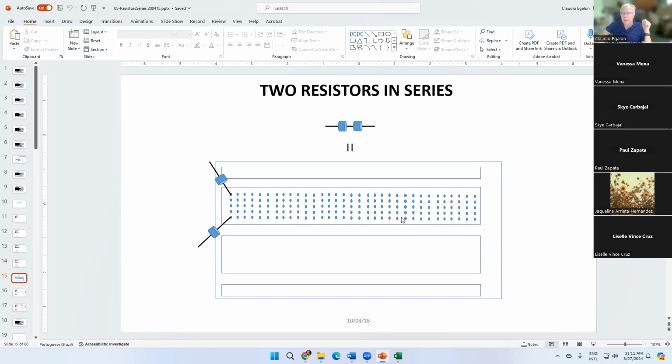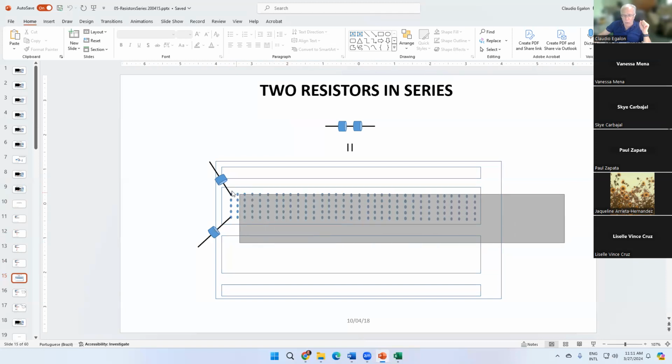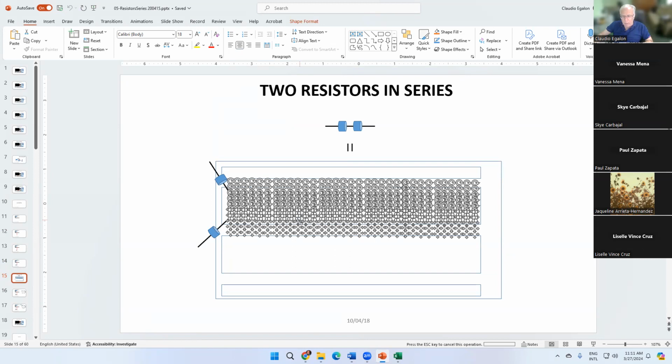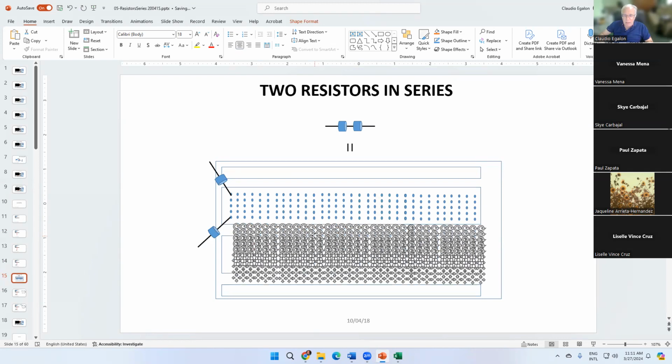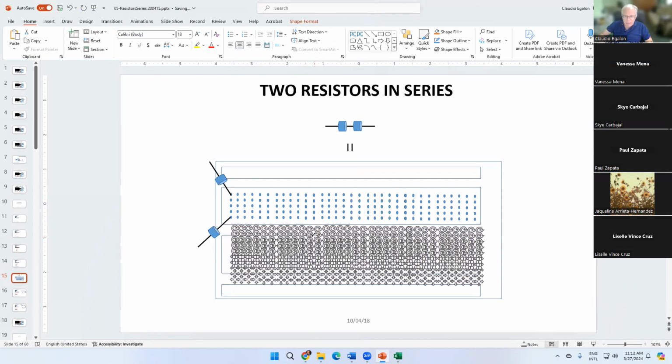It's a larger one than the one you saw on the internet. All those holes are used so we can connect our resistors more easily. Since I'm connecting the resistors in series, one end of one resistor must be in the same column as the end of the other resistor. We're supposed to have more holes in the other part. I didn't do that before because it was too much work, but now I can do it.